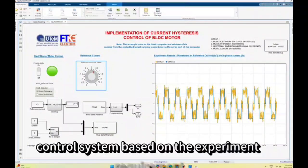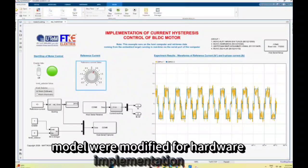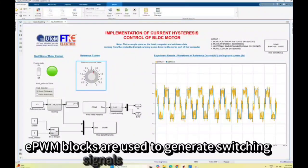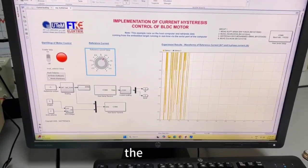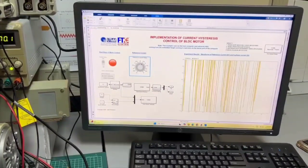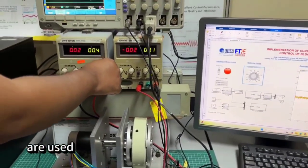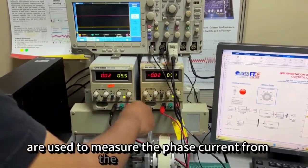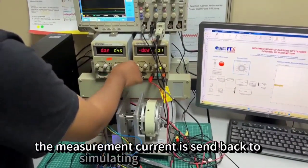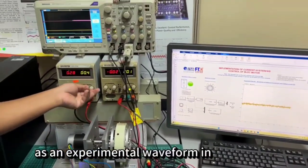Based on the experiment requirement, the original simulation model was modified for hardware implementation. The EPWM blocks are used to generate switching signals for the MOSFETs. The GPIO blocks are used to read the Hall sensor signals, while the ADC blocks are used to measure the phase current from the current sensor. The measured current is sent back to Simulink and displayed as an experimental waveform in real time.